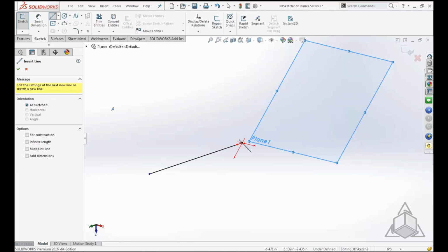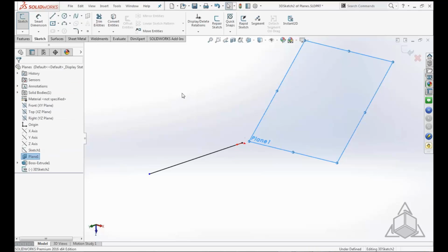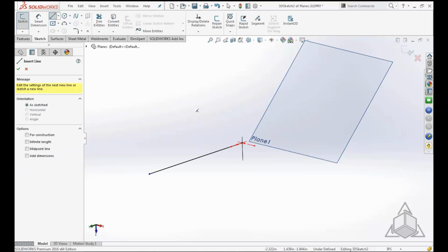In 3D sketching, there is functionality, let me click off on this so we can see that live, that will allow us to move our space handles and lock them to existing planes so that I'm only able to draw in the X and Y directions of that plane. That's what I mean by blurring this a little bit: I'm almost able to create a sketch that's locked to a 2D plane while I'm in a 3D sketch.